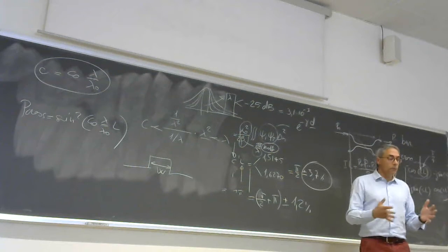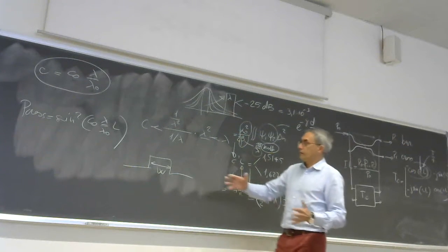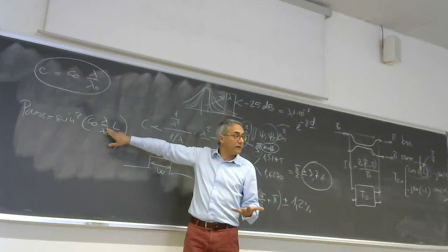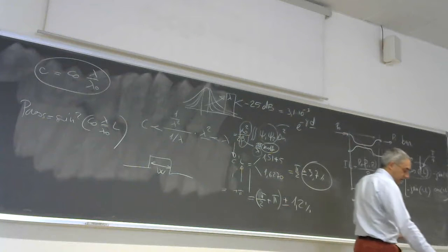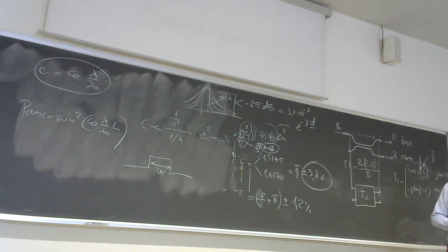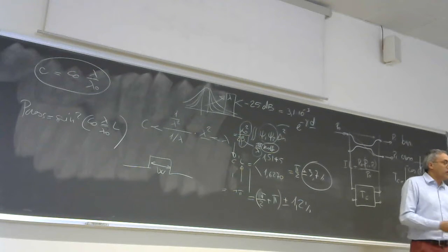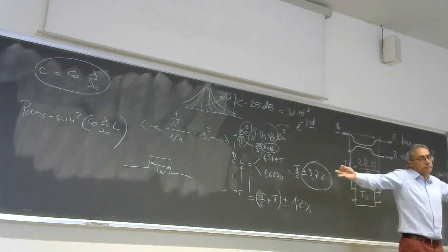If you want to make a coupler that works on this range, it's difficult because the coupling coefficient depends on the wavelength. This is an advanced topic, and we do not enter into how to design a coupler that is not very sensitive to the wavelength, but keep in mind that there is this problem. Your coupler cannot be 3 dB at every wavelength.